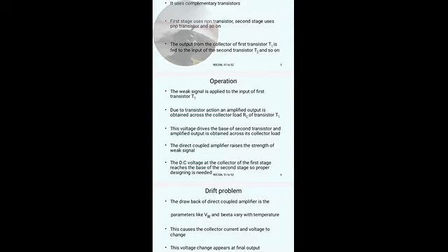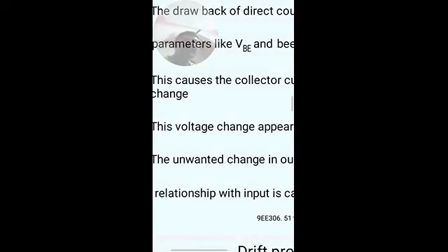This voltage change appears at the final output. So this unwanted change in output voltage, which has no relationship with input, is called a drift problem.